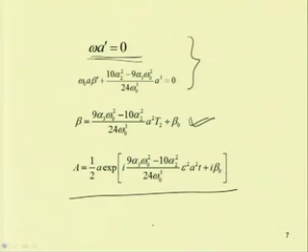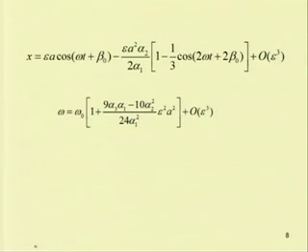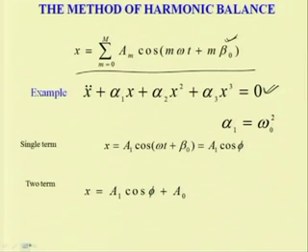So, taking these two as the reduced equations, one can study their stability, and one can study the stability of the whole system. But by using the harmonic balance method, after getting the solution, one has to perturb the original equation of motion to study the stability of the system.